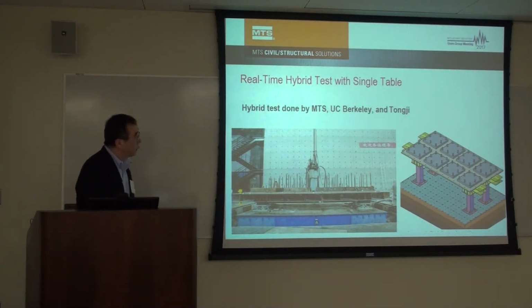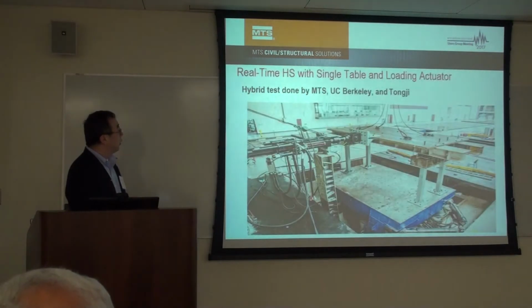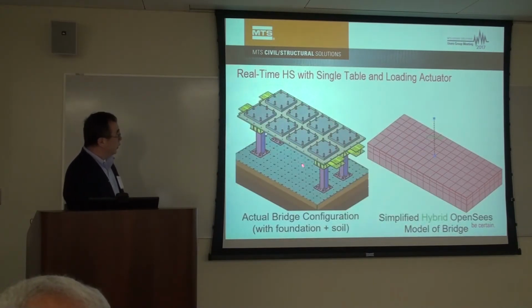This is a hybrid test that we did at Tongji University. In this case, the specimen is a part of the bridge structure. The foundation is modeled by FEA, and the bridge column and bridge deck are tested in the lab. The weight on top of the bridge deck is in the analysis model.